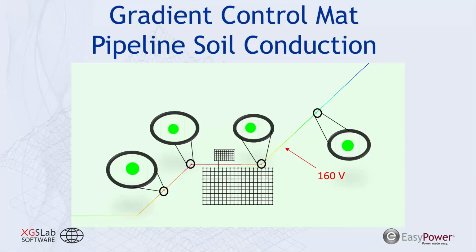So a better method we could use is a gradient control type of method for these pipeline appurtenances. So we can see each of the 4 locations now shows a green indicator, indicating that our touch voltages no longer exceed the compliance limits. And we do elevate our pipeline voltage up to 160 volts just by adding primarily these 2 or 3 gradient control mats. It's picking up that voltage from the grounding system.